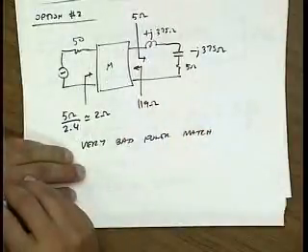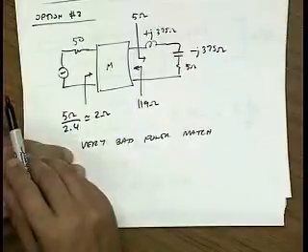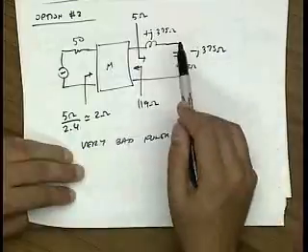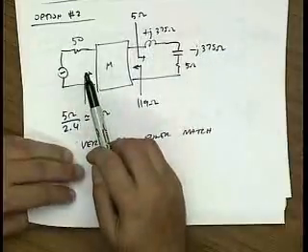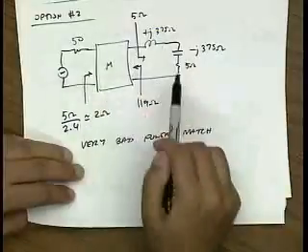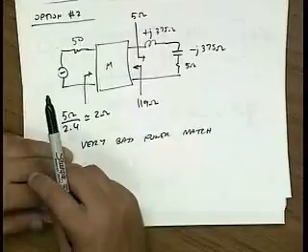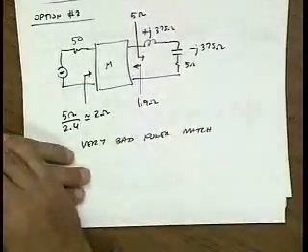So this is 5 ohms, and then I have another matching network to get to 50 ohms. But the problem is that all these components are in front of your amplifier, and any insertion loss adds dB for dB to your noise figure. So all of a sudden you have this complicated matching network, and instead of getting a noise figure of 1 dB, you're going to get a noise figure of 5 dB. Okay, I'm exaggerating, but it's going to hurt you.